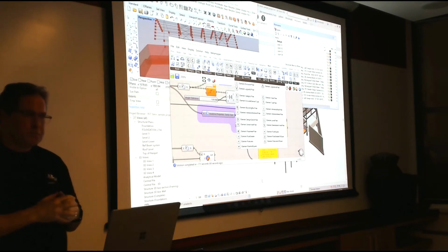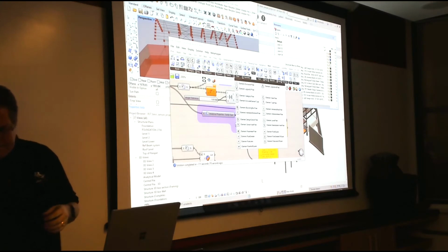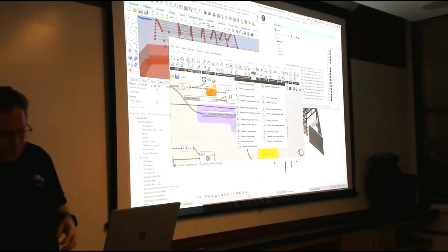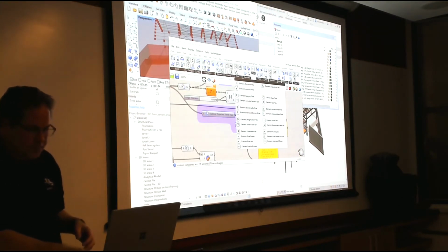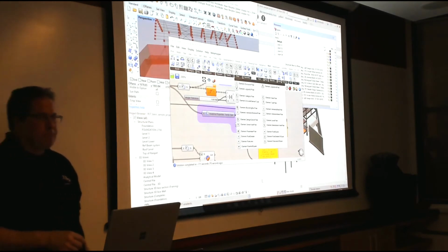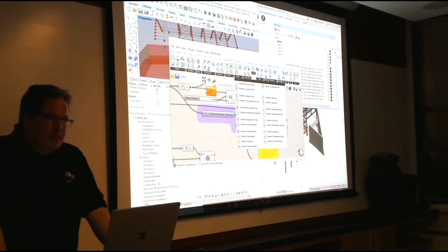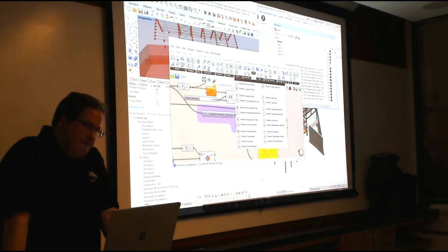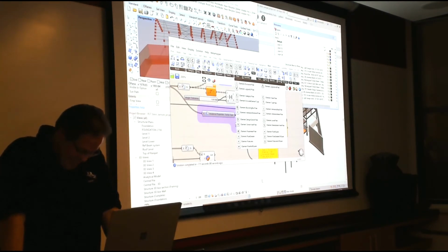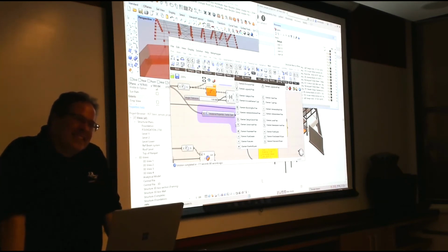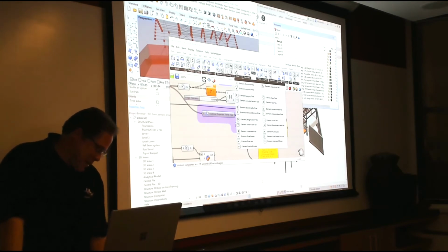Because we are running into that issue right now, where essentially there's a project where there's a lot of like model groups that are constantly being updated. Yeah. We're trying to slip them into Rhino and like have them be able to update in Rhino, and then slip them back into Revit as they're updated. Right, exactly. So what I found is that right now there's no current direct method, like component, battery method to do that. Right, you have to write your own Python script to do it. Right. Yeah, because we haven't got there yet.